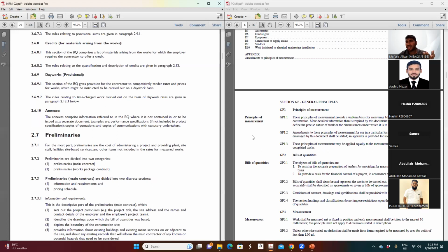We have a record. If we don't have a record, we will go to the supplier and ask, give me the quotation for tile. So what we did, we had around 9,000 square meter of porcelain tile in the project. Not 9,000, even 13,000. I remember 13,000 square meter of porcelain tile in the project. We know the material cost is 40 dirham per square meter. So my expectation is 150 dirham per square meter, including supply and installation, for this tile.